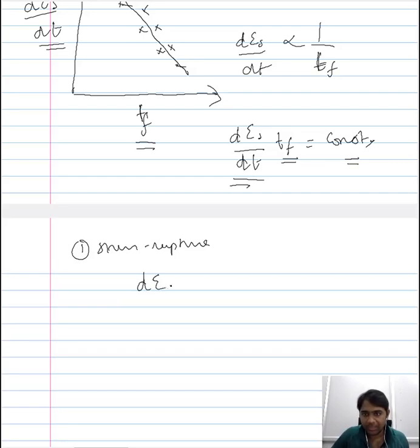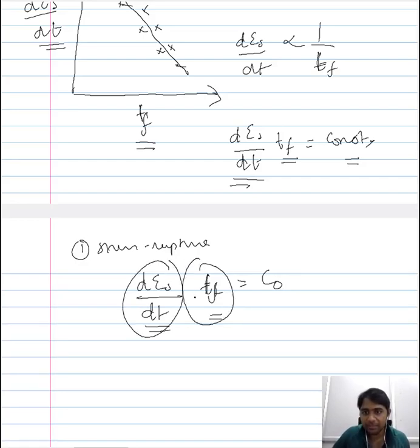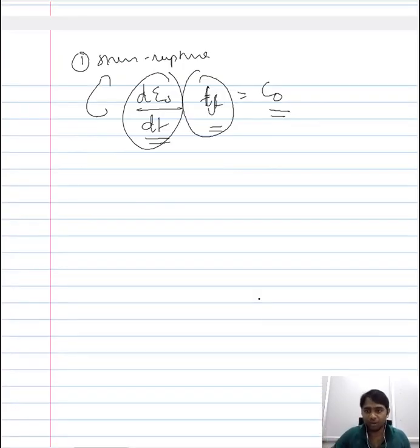So you are able to identify from the product of the time taken for the failure and the minimal creep rate, which you would get from the numerous stress rupture tests that you could perform, the proportionality constant C0. So these two values you will be able to calculate from the numerous stress rupture tests that you perform, and from that you can then identify the proportionality constant. And once you have realized the proportionality constant for a material, then using this relation you will be able to predict, for a given steady state creep rate, the time taken for the failure.